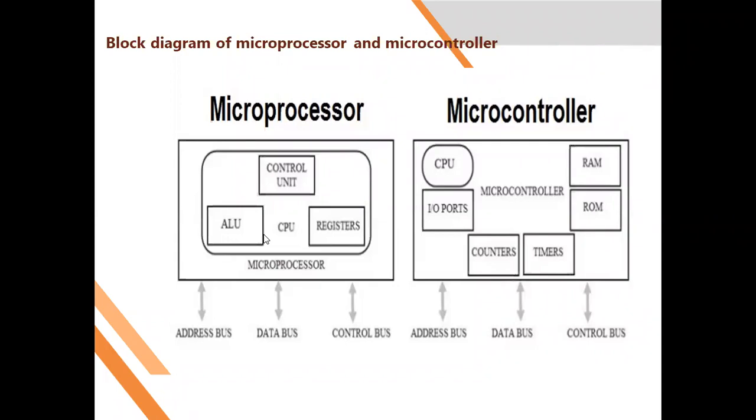What is the use of that IC 8255? It acts as input and output pins, okay, to give the data to the microprocessor and to take the data. That is not the case with microcontroller. Why? Because for the microcontroller you have inbuilt input and output pins. So with the help of those pins you can give the data, and with the help of the same pins you can take the data. Okay, so timer, counters to create the automation, RAM, ROM to save the data.